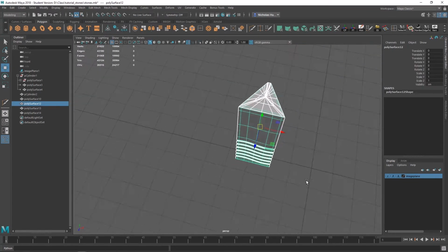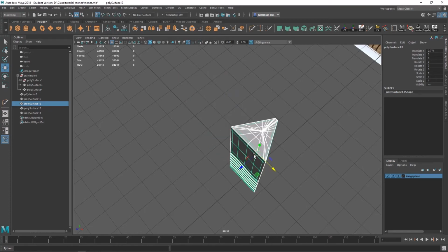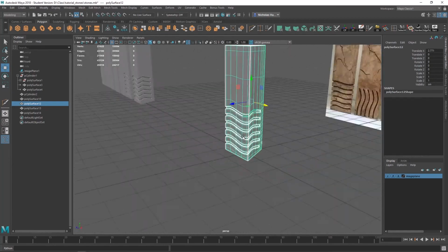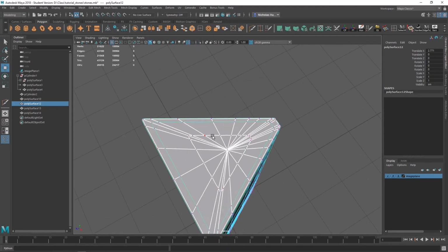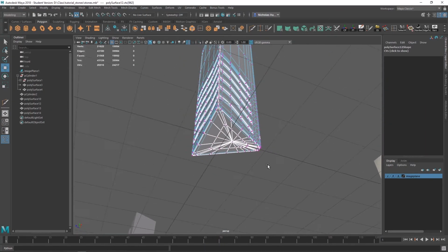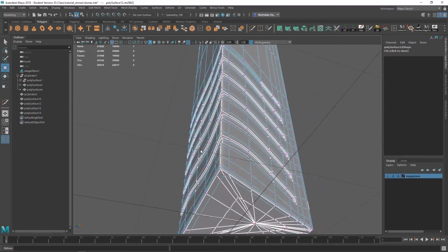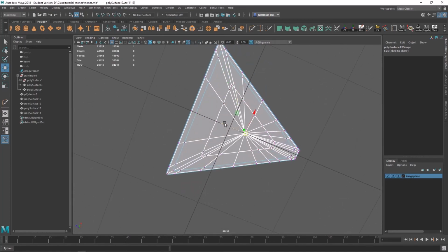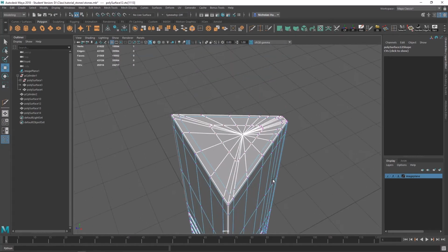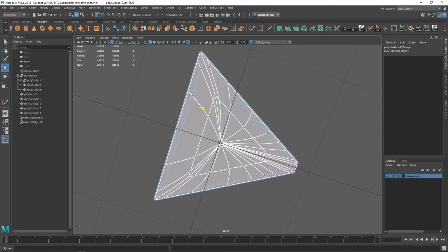So I want to make this to the center. So with W selected, grab this handle here. We want to snap it here, so I'm going to hold down X and just pull it along. Should snap. That should be the center. Cool. And now, if you want a point on your mesh to represent its exact center, we know that when we created it, its exact center was the world center. So we could just take this vertex, and, well, it might be better this way. Do the bottom one first, it'll be easier to tell. We snapped it there, and then take this vertex, wiggle it a bit, and then same deal, hold down X and snap it there with middle mouse button.